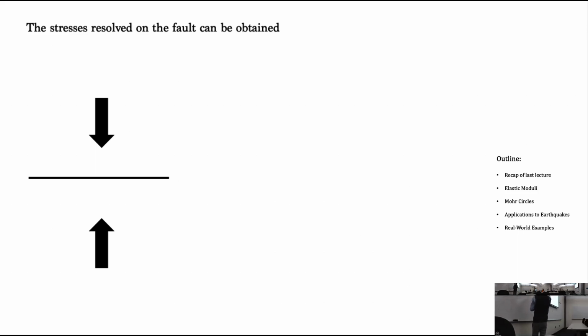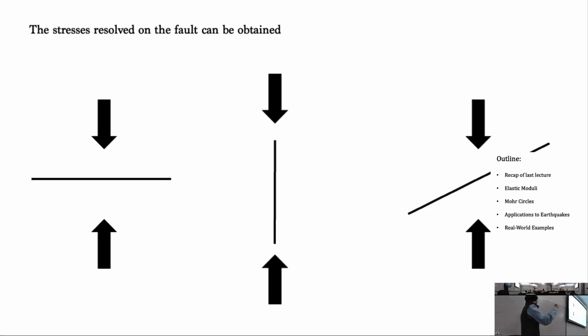of normal stress on this axis, which we'll call sigma n, and shear stress on this axis, which we'll call tau. So tau is going to be equal to 0, right? What about sigma n? Yeah, it'll just be the force acting on the plane. That's pretty simple. Let's call it alpha. So alpha is the normal stress, 0 is the shear stress. This point on these coordinate axes, and we'll get to these axes in a moment, is right there, right? We all agree on that?